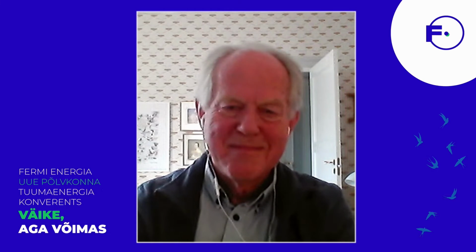Thank you, Hans. I see that you have joined us online for some questions, and we have a couple from the audience. So the first one, do you have any thoughts on disposal of high-level waste from the possible Estonian SMR? Well, there is a lot of experience in the world, not least in Sweden and Finland, on how it could be done. I know that Estonia is looking at deep borehole disposal, which today is not a mature technology, but could very well be developed until it's time for you. But it all depends on what geological conditions you have in the country.